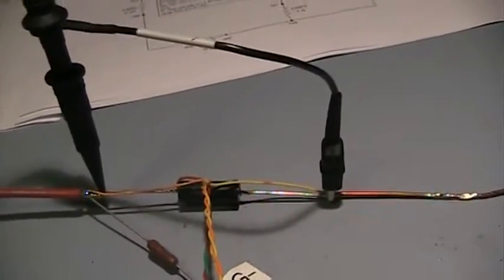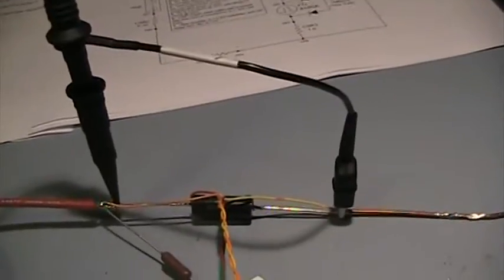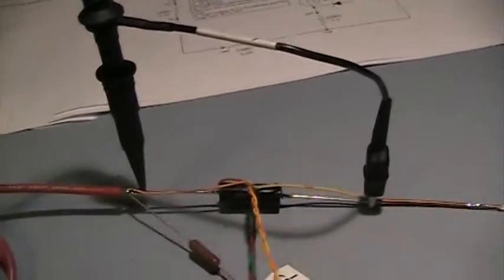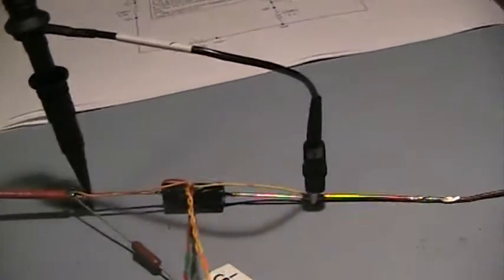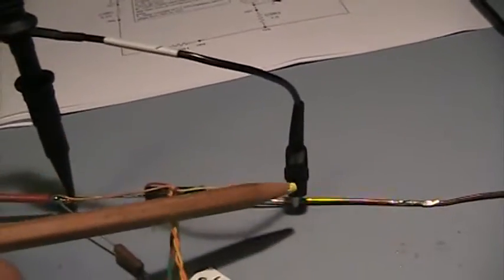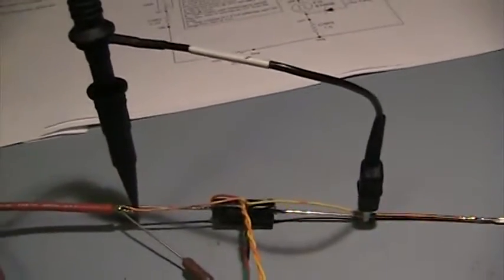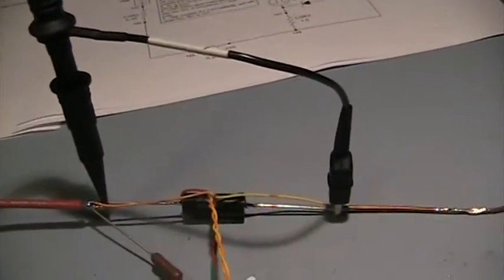Now the second source of potential error in these circuits, particularly when they're oscillating at high frequencies, is inductive pickup. And this is particularly a problem when we're using single-ended probes like we are, where you have this ground lead coming off the probe. In this case, this is probably about a 4 or 5 inch ground lead, reference lead.